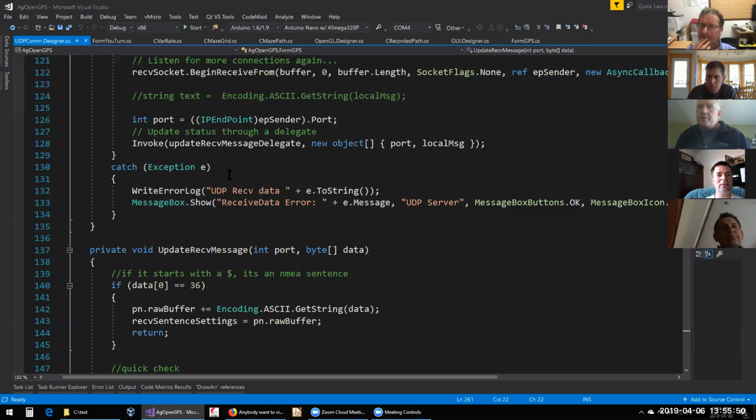The numbers are bouncing around all over the place? Yeah, and very high numbers, about 42 degrees or something like that. Oh, goodness. So that's why I deactivated the MMA, and now it's driving much better. Shoot. I have to look what the problem is. Because the board schematic is just the I2C lines in, that's it. Yeah, and the I2C should work, because when the engine is off, it's working well. Maybe it's too cheap. I bought a Chinese one. I don't know. That's a weird one.